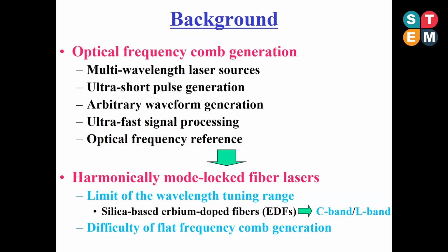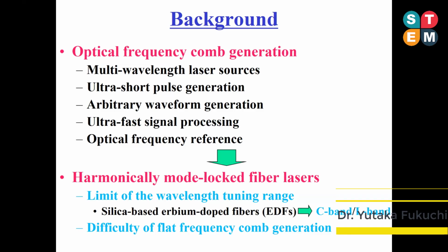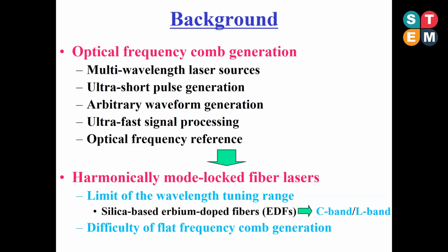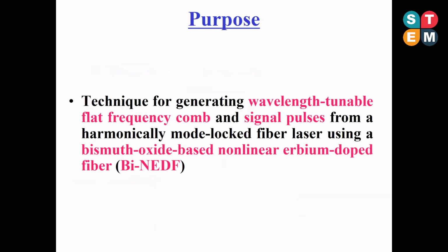However, the range of the wavelength tunability is normally limited to the conventional wavelength band because these fiber lasers usually employ silica-based erbium-doped fibers as the intracavity gain media. In addition, it is also difficult to generate a frequency comb with good spectral flatness.